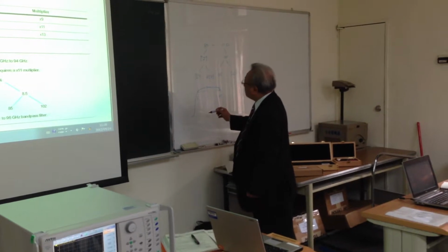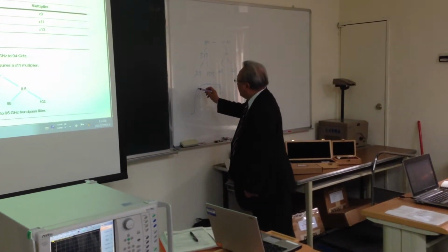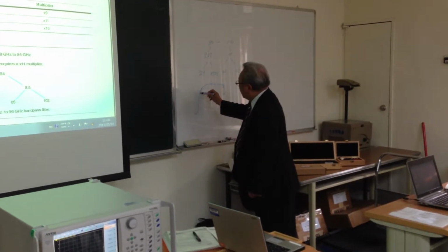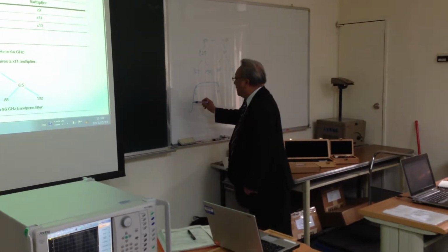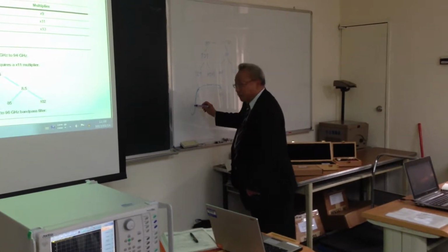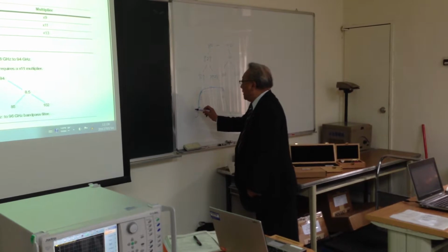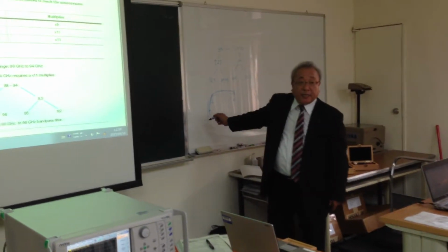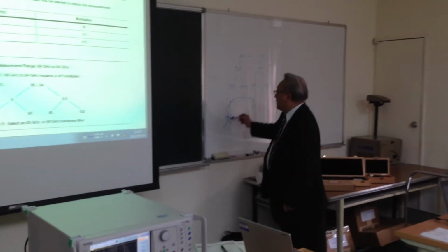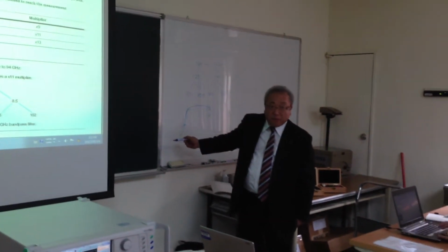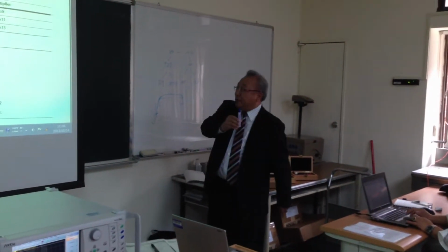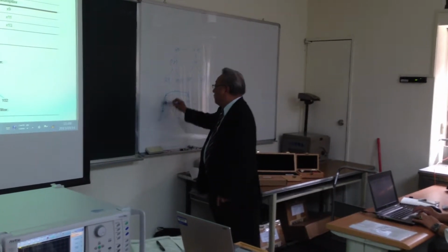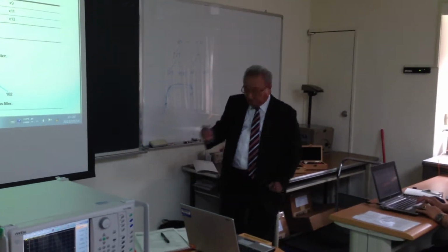You need about 15 to 20 dB rejection of any image. If the image falls at a similar position, then we can reject 20 dB maybe. So yes, the question is very important: the slope, how to make it.